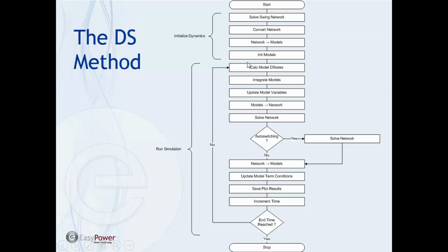It also means that the power flow solution after entering stability is different than what you would have in a regular power flow simulation. If you scale a motor, for instance, in power flow, it scales both watts and VARs down. That does not happen in dynamic stability because the scale factor is applied to the mechanical load on the shaft. So your VARs are not necessarily going to drop.